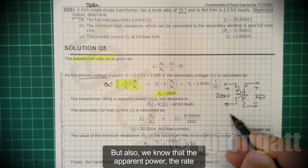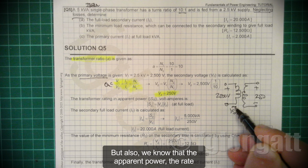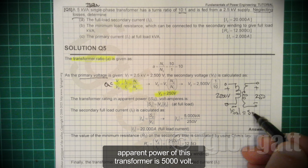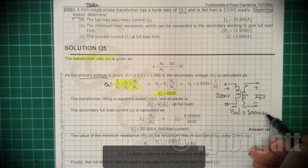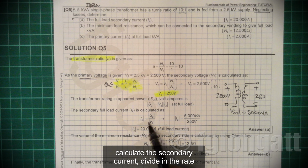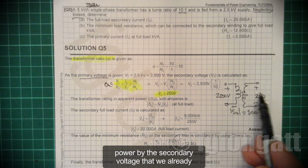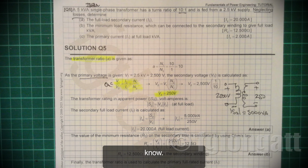We also know that the rated apparent power of this transformer is 5000 volt amps. So it's very simple to calculate the secondary current by dividing the rated power by the secondary voltage that we already know.